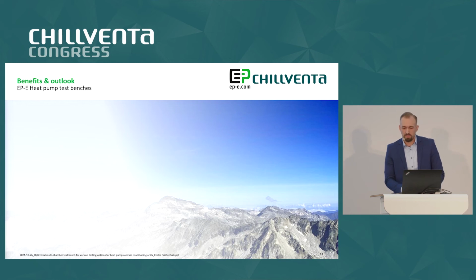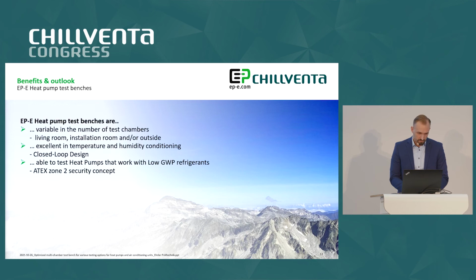Here I'd like to give you an overview of the benefits of the test benches and an outlook on what we have in our project pipeline. Heat pump test benches are variable in the number of test benches: living room, installation room, and outside. Excellent temperature and humidity conditioning, closed loop design, able to test heat pumps that work with low GWP refrigerants, ATEX Zone 2 security concept.